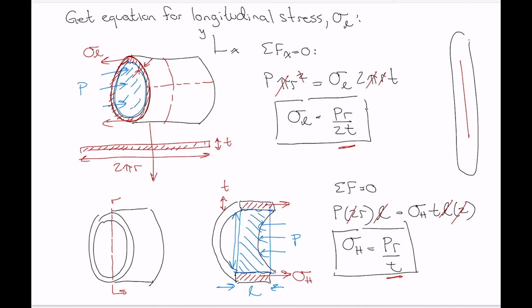That's because as steam is produced within the hot dog, and you've got the thin casing around it, it becomes a thin-wall pressure vessel, and the stress in the hoop direction is twice the stress in the longitudinal direction. So you will always get that split occurring like that and never like that. There you go. It's good weather for barbecuing now too. So very, very timely lecture for us.